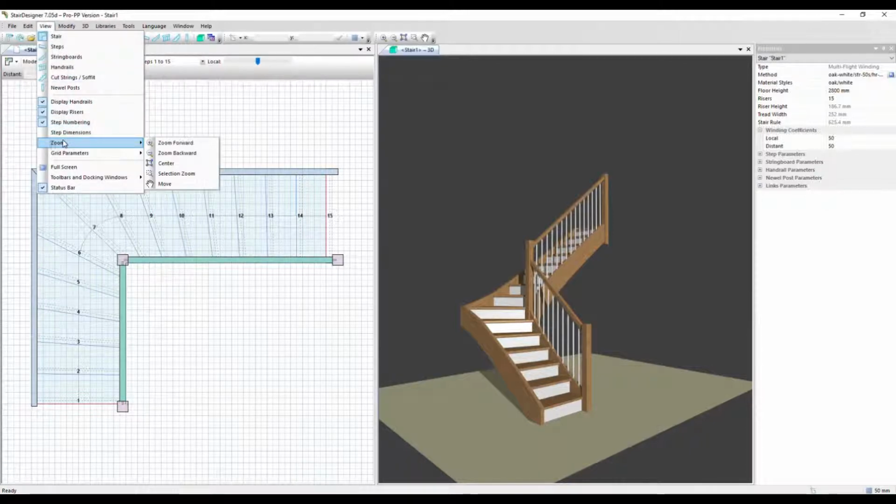We've got some zoom options, but I want to focus now on the grid parameters. We recommend setting it up as show grid and the grid spacing on low. Can adjust it here, and align to grid, have that checked as well. You can then see down here 50mm is shown. That is the current spacing of the grid.